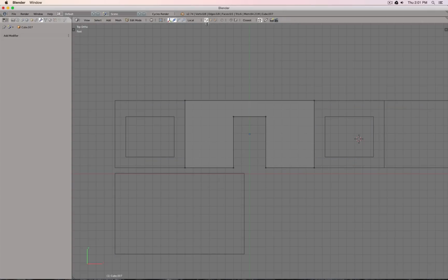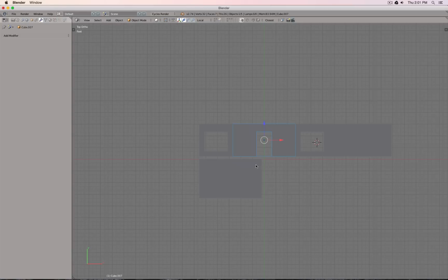Let me remove this one, actually this line I didn't really need. Yeah, that face I meant. All I need is just this line, because the laser cutter will cut along these 3 lines like a U, and then it cuts along this line, and then I have a door which I could either put back in, rotate, glue in with a pin or something, or have it on a hinge.